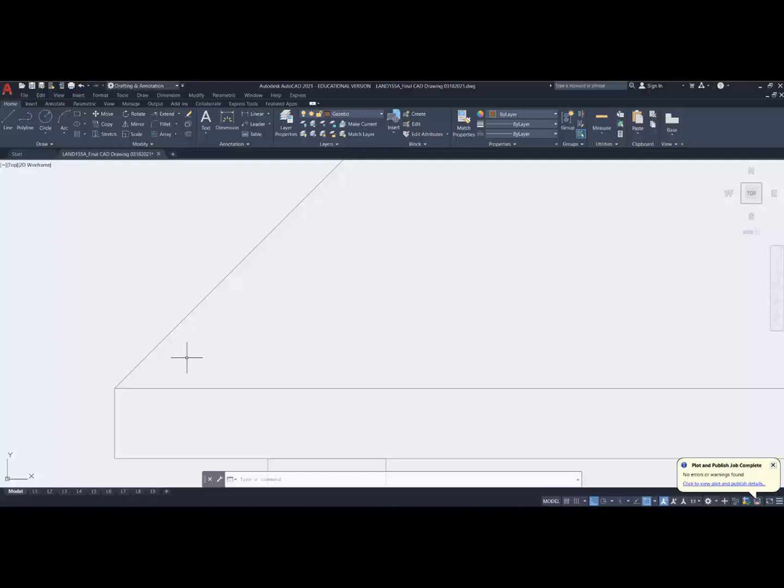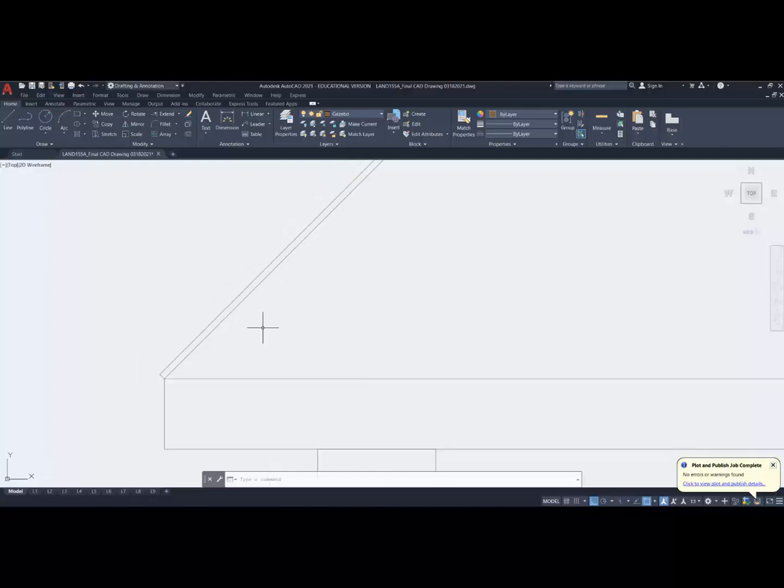We're going to convert this to a sectional drawing, and we work from the outside in. So asphalt shingles or cedar shingles could be shown as a 1/2 inch thickness typically, or a bit more if you're using any sort of cedar shingles, and that's how we're going to draw that particular element. It's about a 1/2 inch in thickness. Now there's multiple layers here, and we don't need to show it. And we will note the different finishes, but we won't actually draw them because this shingle sits on top of, it could be an ice and water shield or building paper, and then you've got the plywood.